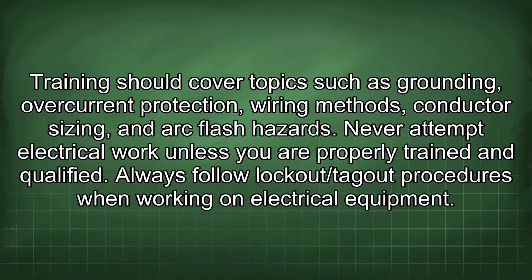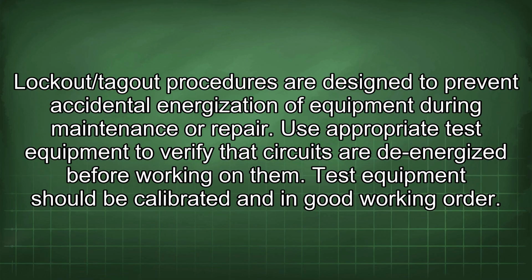Always follow lockout/tagout procedures when working on electrical equipment. Lockout/tagout procedures are designed to prevent accidental energization of equipment during maintenance or repair. Use appropriate test equipment to verify that circuits are de-energized before working on them. Test equipment should be calibrated and in good working order.